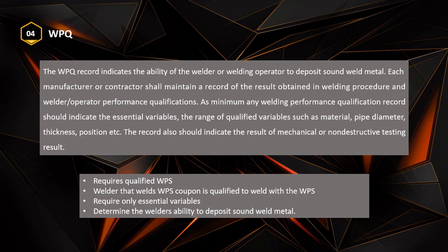The WPQ requires a qualified WPS. A welder that welds a WPS coupon is qualified to weld with the WPS. It requires only essential variables, to determine the welder's ability to deposit sound weld metal.